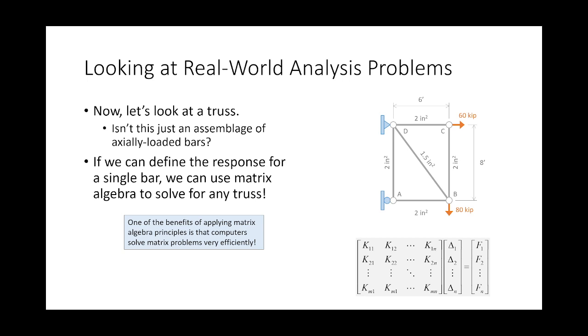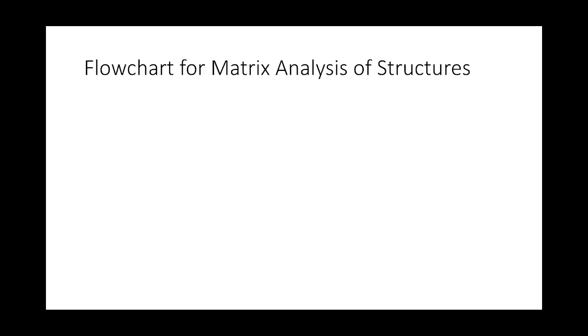So what we can do is express the structure with this collection of spring constants and forces and solve for the displacements. And that's how a computer analyzes structures, whether they're determinate or indeterminate. And the best part is we can define a single method that works across the board. So this is how these structural analysis packages work.